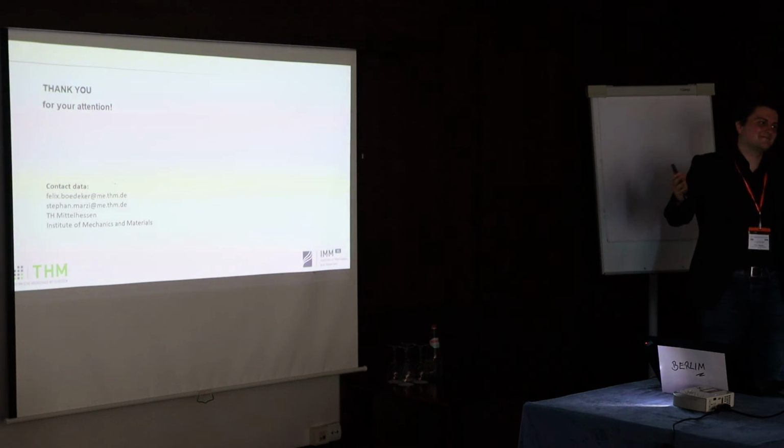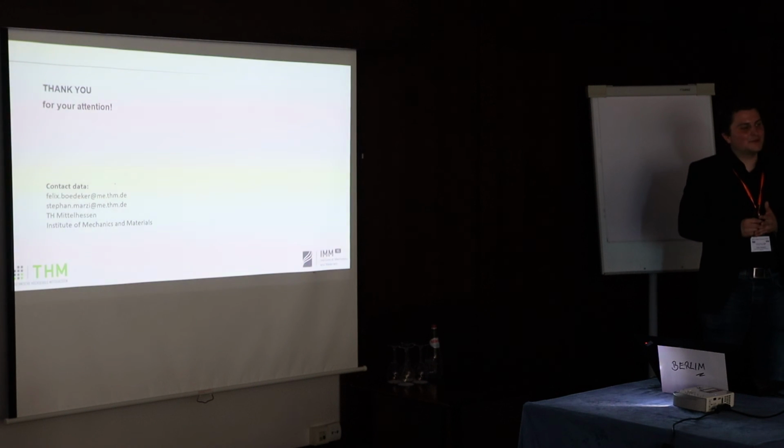Anyway, my second question is more... I'm not really sure how it is for this problem, but we did also work with these DCB geometries and so on. I've looked into your prediction, but we also have oscillations in the load displacement curve, which is not usually what you get. But the prediction with the simple linear triangular CZM works very fine with these DCB geometries, I'd say better than what you presented with your FFT RVE homogenized.